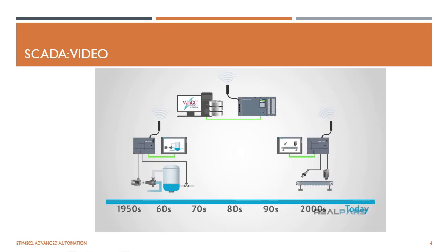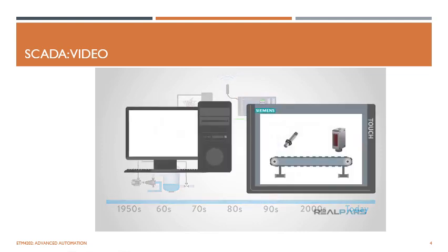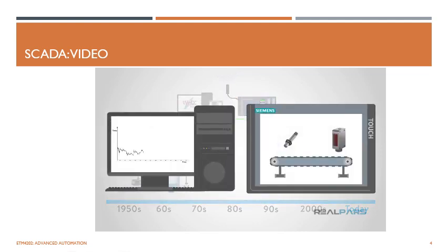Data collected from the field devices is then passed to the processors, such as PLCs. From the processor, the data is distributed to a system of network devices. These devices may be HMIs, end-user computers, and servers. On the HMI and end-user computer, graphical representations of the operations exist for operator interactions, such as running pumps and opening valves. This data may also be analyzed and used to enhance plant production and troubleshoot problems.